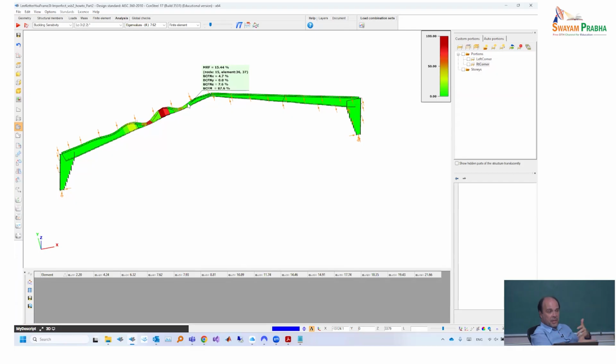So they are realistic deformations, so why not calculate deformation energy from them? It's just simple stiffness matrix multiplication. We already have the stiffness matrix for a section. We multiply the stiffness matrix with the deformation and we calculate deformation energy.